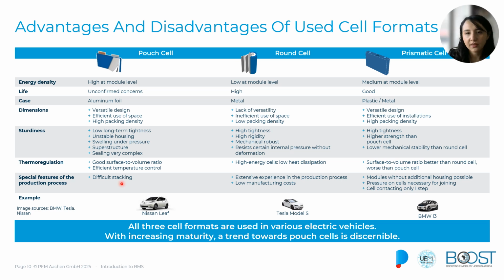The problem with this is that they are maybe a bit difficult to stack, and also that the system itself has a swelling mechanism. So when you are charging and discharging, this aluminum foil may expand and contract a little bit, so you need to create the mechanical enclosure to avoid that being a problem.